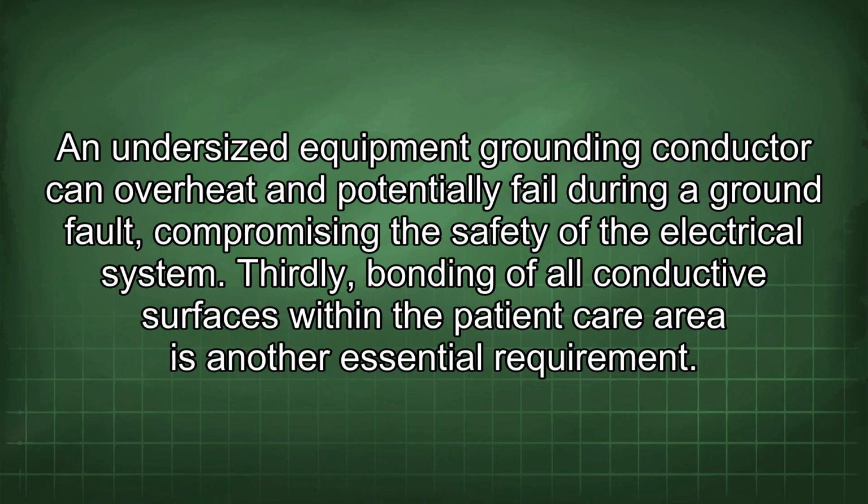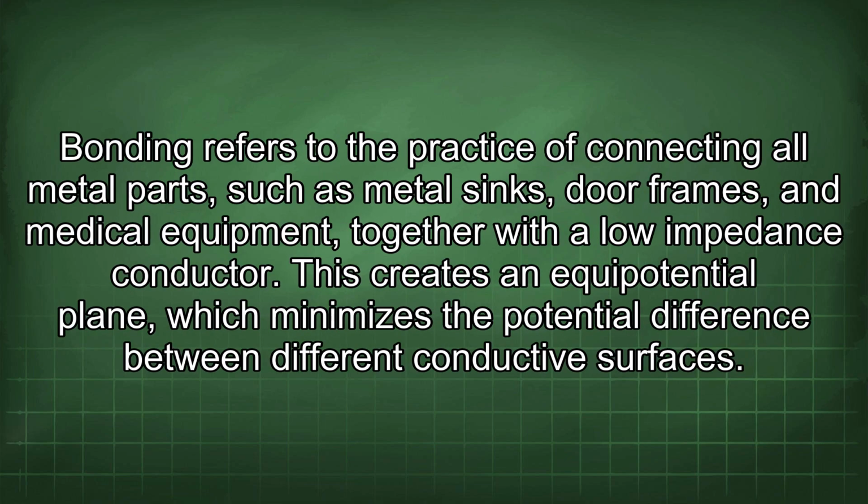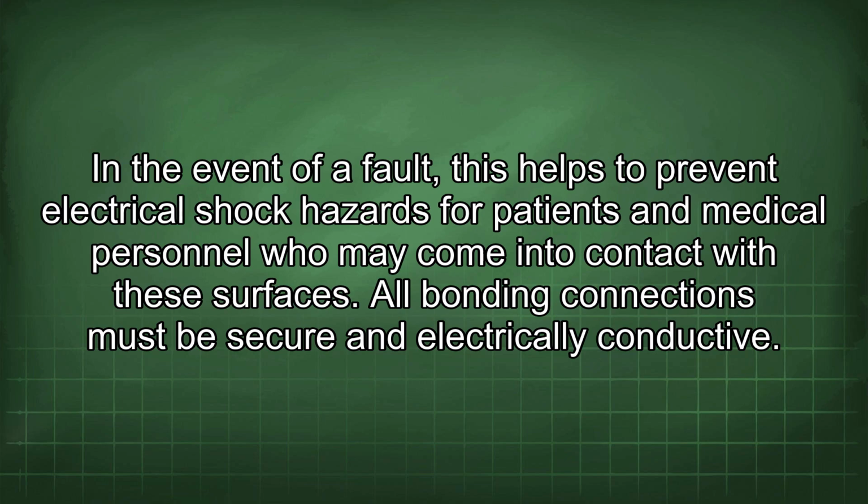the electrical system. Thirdly, bonding of all conductive surfaces within the patient care area is another essential requirement. Bonding refers to the practice of connecting all metal parts, such as metal sinks, door frames, and medical equipment, together with a low-impedance conductor. This creates an equipotential plane, which minimizes the potential difference between different conductive surfaces. In the event of a fault, this helps to prevent electrical shock hazards for patients and medical personnel who may come into contact with these surfaces. All bonding connections must be secure and electrically conductive.